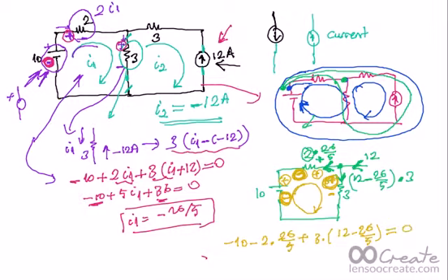On this direction I always take the first polarities. You can take the exit polarities too, but I'm just using these ones. If this gives us 0, then our solution is correct. If I do my calculation, this is minus 10 over 4 and plus 20 over 4, which gives us 0. So this part is 0, and 0 equals 0. My solution is definitely correct.